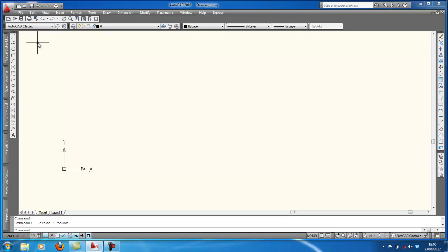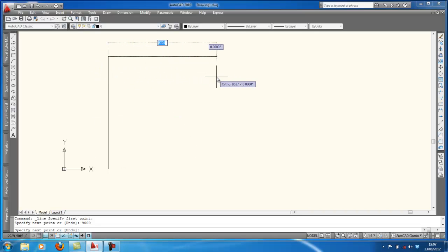it. So let me demonstrate two different ways of drawing, and I'll show you differences, because we will also explore several different commands during this session. So first I will go to a line. I will start from this point, a bit away from UCS, click upwards, type 9,000, enter. Then I move to the right and type 9,000, enter again. Now I move downwards, type